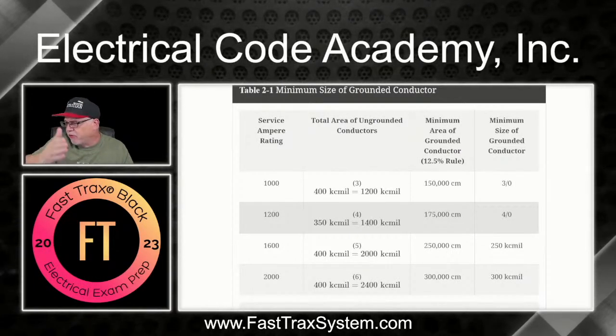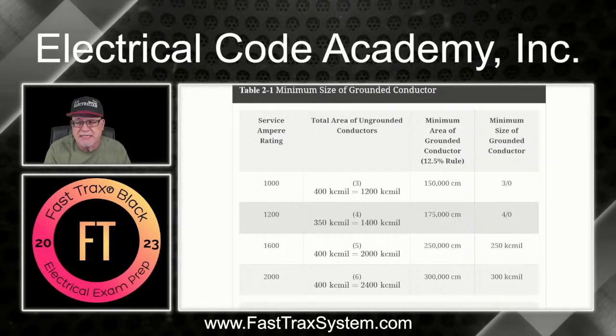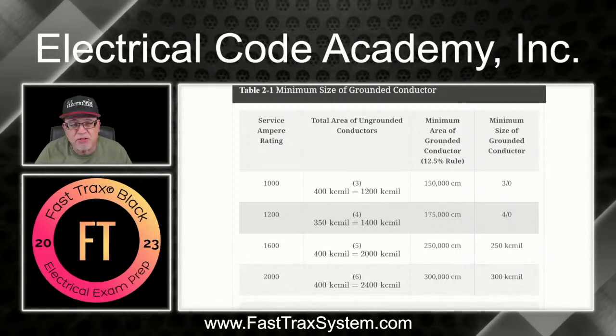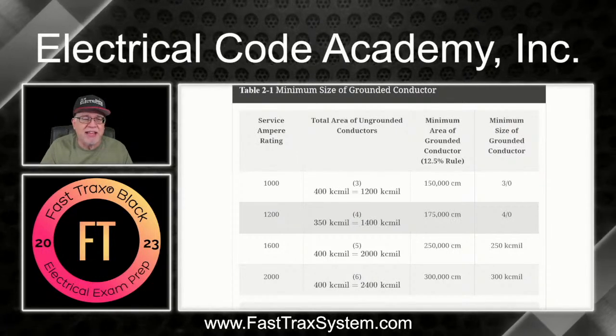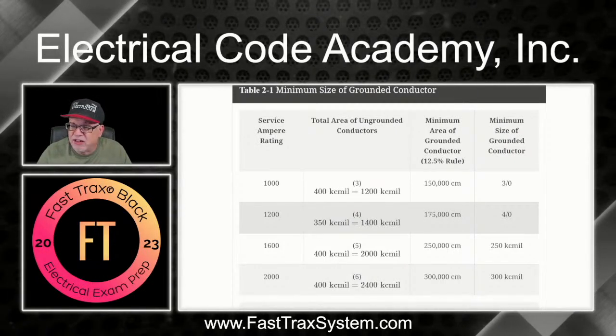Same thing. If you go over to the table and look at the 175,000, you're going to see that it doesn't equate, because the 3/0 was 167,800, right? But the next size was 4/0, and 4/0 is 211,600. Well, that's okay. That can handle the 175,000. So guess what? I just go up to the 4/0. And that's all it's done here for you.